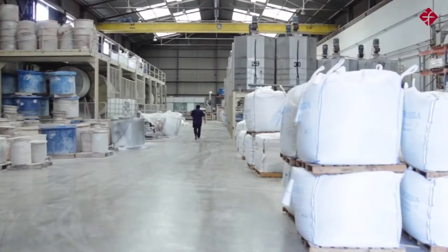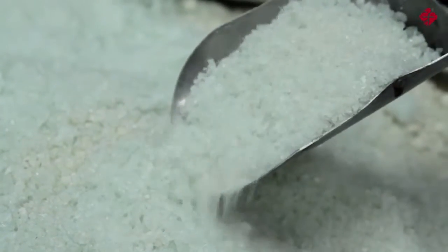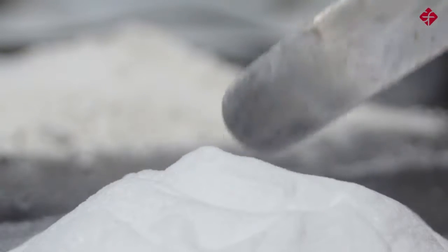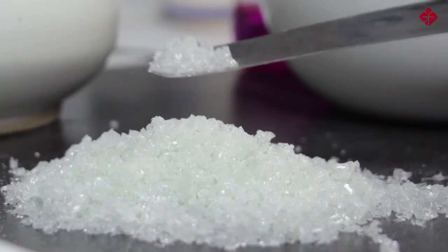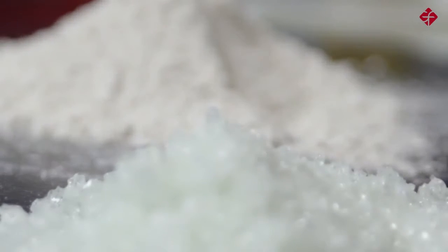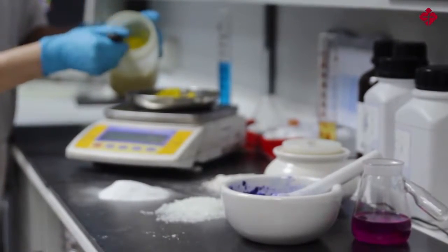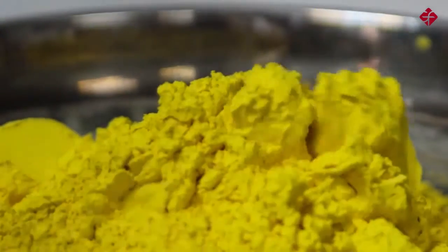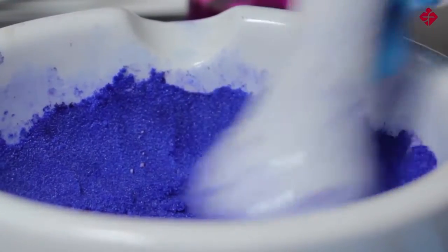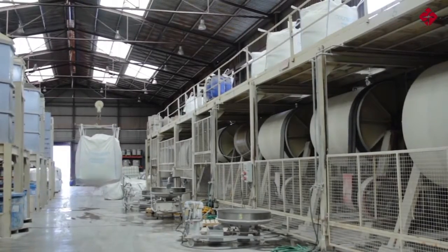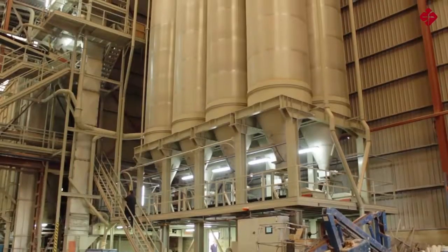The ceramic process begins with selecting the raw materials that we mix to create the tile, basically clay, feldspar, sand, carbonate and kaolin. As the raw materials are used just as they are extracted from the mines and the quarries, the first and most important thing we do is check the uniformity to ensure their properties remain consistent. To do this, the materials undergo a mechanical milling process that disperses the particles and reduces their size. Gayafores has its own glazing warehouse, silos and an unloading bay for the treated clay.